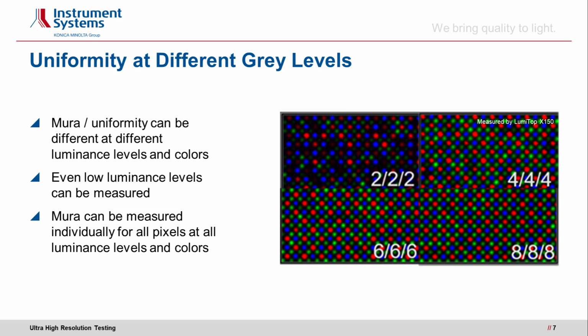We see in the upper left, the behavior of individual pixels varies greatly depending on its location on the display and also on its color. And this variation is not comparable to what is seen in the brighter images. This means that for proper de Moire or pixel correction, it's necessary to perform detailed pixel analysis at each gray level that is to be corrected.